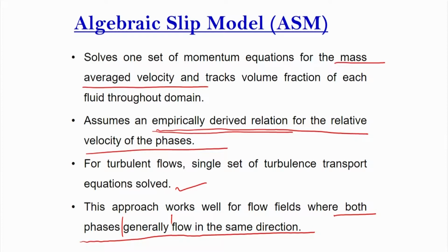Why? Because in that way the slip velocity actually becomes lower. So this is the overall approach used in the algebraic slip model, one of the initially developed models which starts solving the multi-phase flow equations from one dimensional to the three dimensional domain. But because the computational power was not very high, the equations were developed in this way so that you can still solve typical multi-phase problems and get some solution, and we will discuss what kind of solution you can get from it.